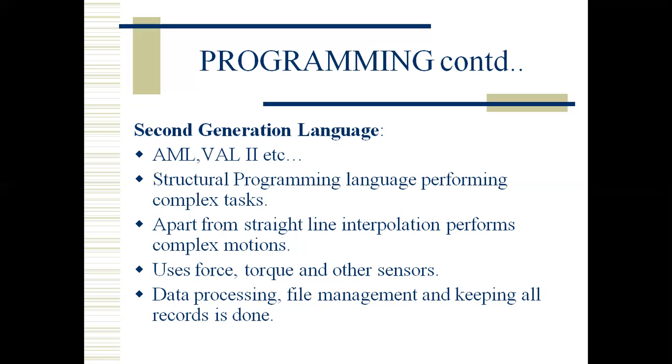And the next one is data processing, file management, and keeping all the record system. And here, what is the defect that we have observed in the punched tape? If the punched tape has been prepared, the same punched tape cannot be utilized for dimensionally changed work parts to be utilized for manufacturing. But in the case of structural programming or interpolation performance in the second generation languages, a computer device will be utilized, and there the sequence of instructions will exist. If further we need to change the dimensions, we can just edit the program.